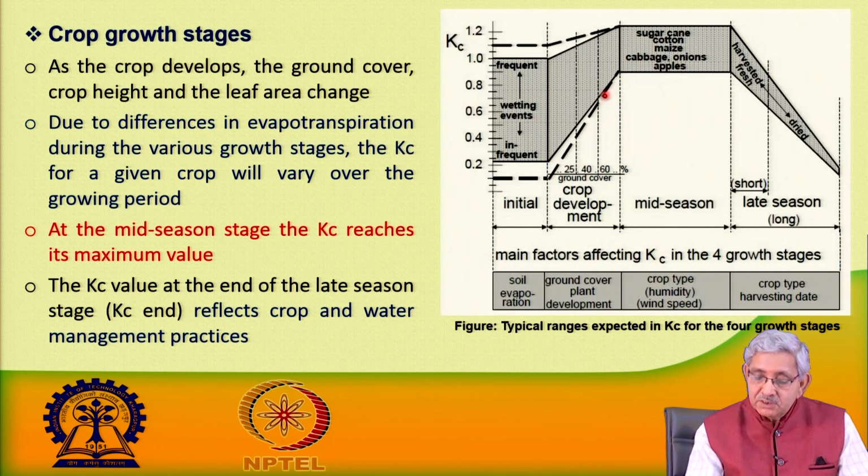This graph shows the nature when we are maintaining certain soil moisture deficiency, whereas here we see frequent irrigation. Particularly in the case of a micro irrigation system, we are not maintaining a deficit condition, we are maintaining an ideal condition where the crop does not have to go through any moisture stress. So, this is more relevant for micro irrigation.